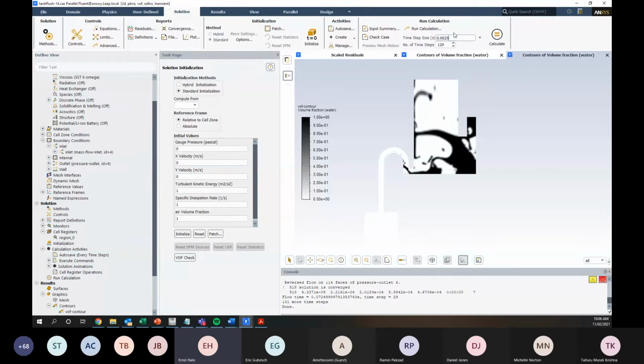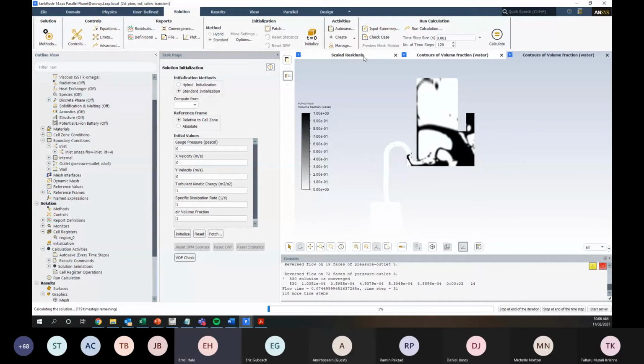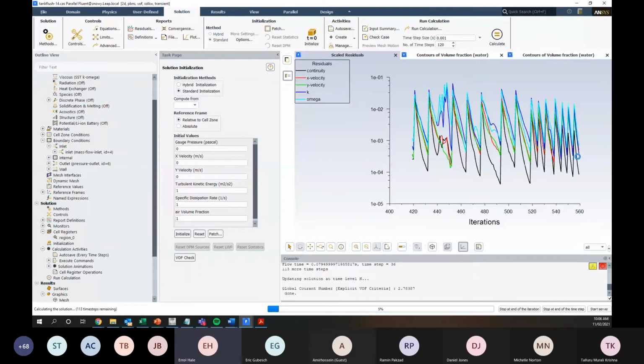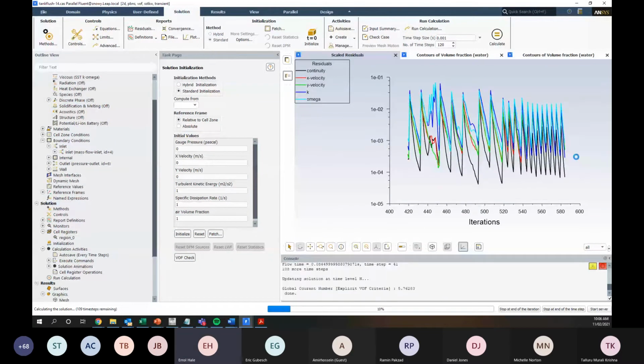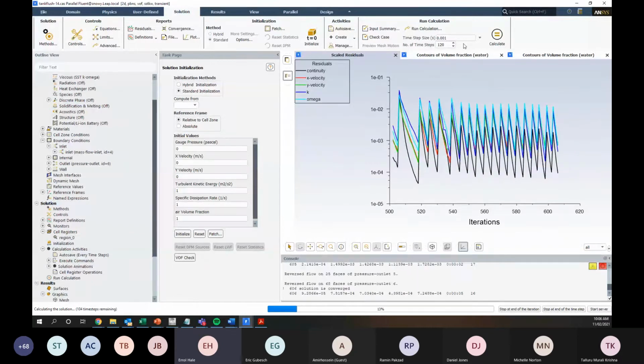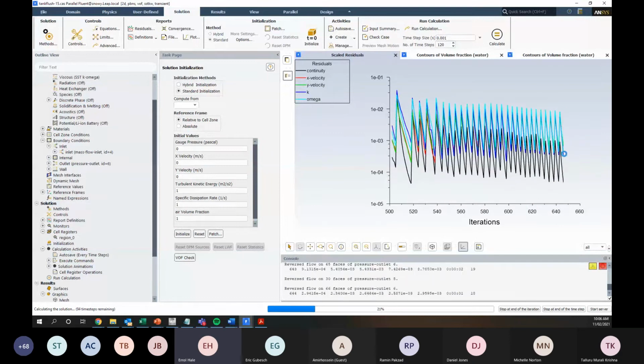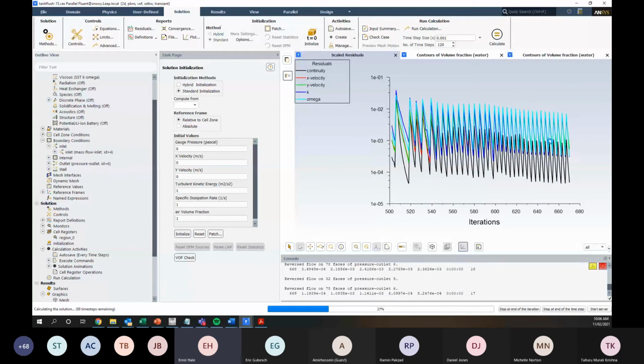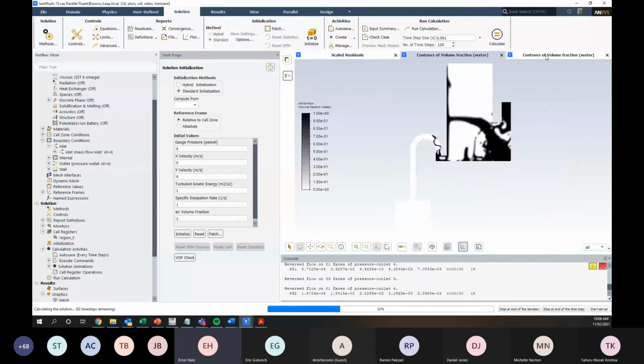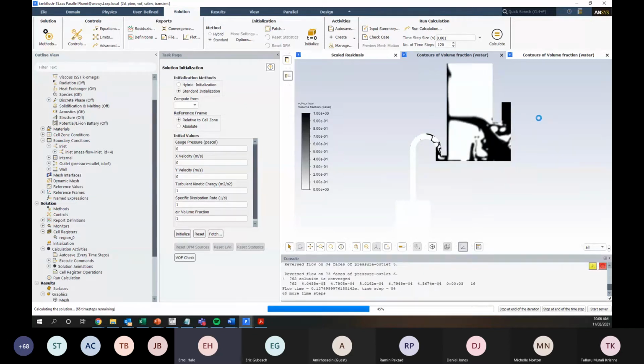But I might like to reduce that time step size by some factor, just to see if I can get a little bit better convergence like that. That's what you want to see. Few iterations per time step, and it runs through, you'll actually save time. So that's less than half the time step size, but it'll do more time steps in the same time, because we're getting better convergence behavior. And you can see this is obviously set up to only record every few time steps, so this updates every few time steps.